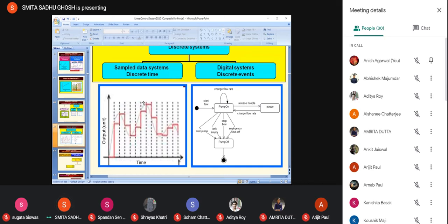So here, what I mean by 0th order hold, I'm not going to go into the details of it. What I mean to say is that the previous value is held constant till the time the next output occurs, that is the next instant where the pulse value changes, and then again it is held constant for the remaining interval. So after the 0th order hold has been applied, of course, the output is continuous.